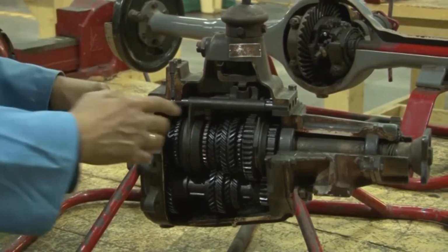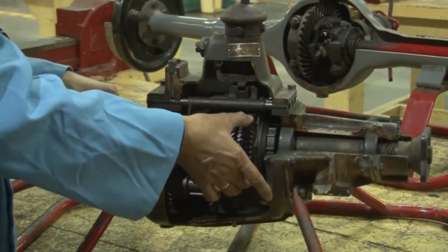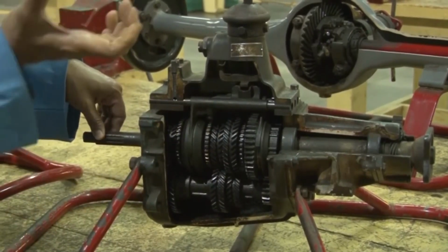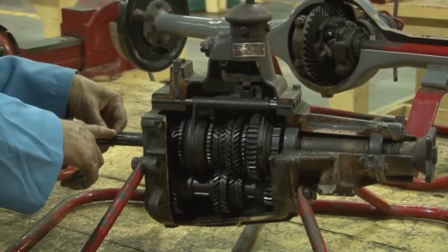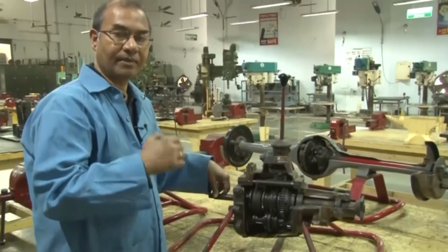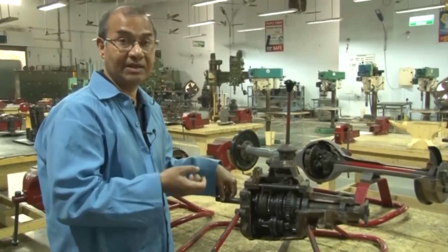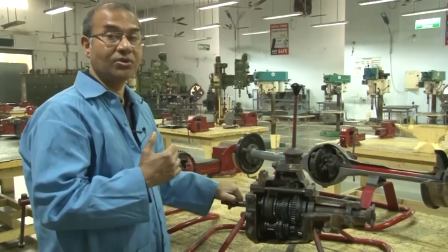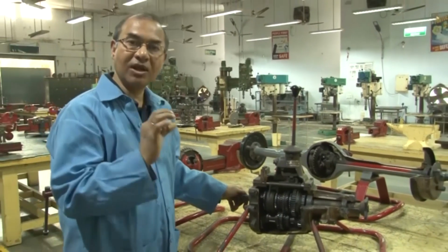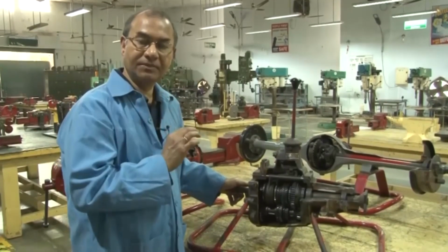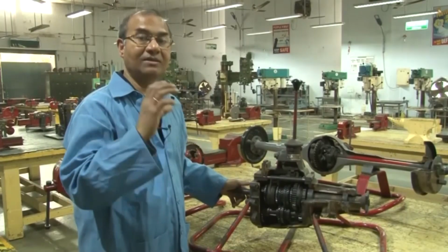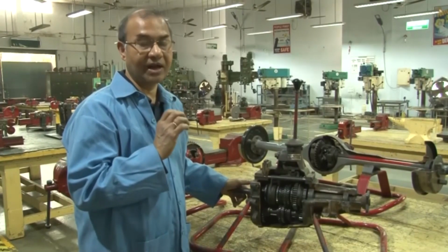In that case, what happens? You have to transmit with a higher transmission ratio. So, from a bigger gear, it has to go to the smaller gear at the output, and vice versa when you need to have a smaller RPM, for example, in the first gear or in the second gear. In the first gear and second gear, the input shaft has a smaller gear. By smaller gear, I mean the number of teeth will be less, and accordingly the diameter will be less.